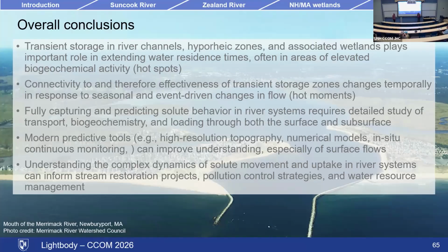You have to calibrate the voltage response to rhodamine, and there's also an interaction with dissolved organic matter and chlorophyll within the area, so you often have to do a field calibration as well. But yes, you're looking at the voltage from the fluorescence response and calibrating that